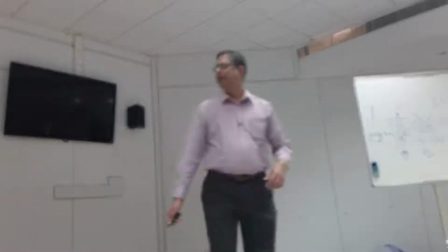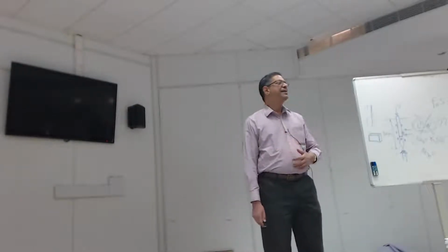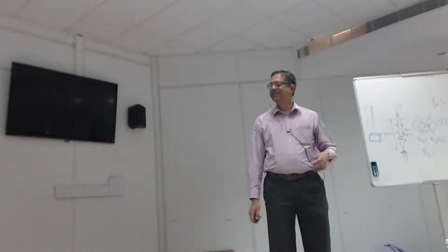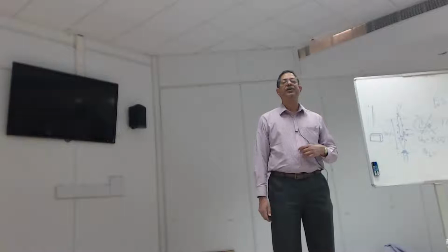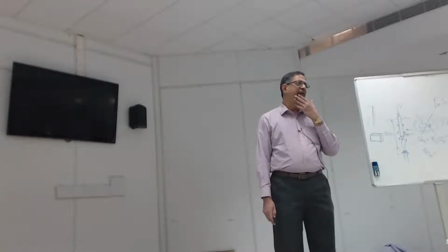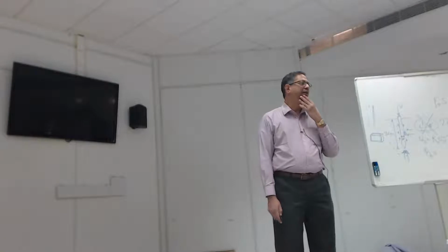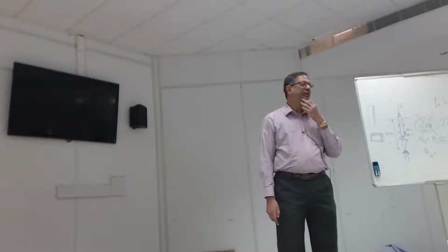Wood is even more warpy, and people are unsure. That's why you've got a lower factor of 0.66. And in any case, there are not that many wooden piles being used around the world anymore. And then you adjust your Ks factor according to relative density. These are very simple Tomlinson style calculations. So they give you an answer. They're good to pass exams, but when you actually design these things and it costs you real money to build them, you will very soon realize they're not so good.